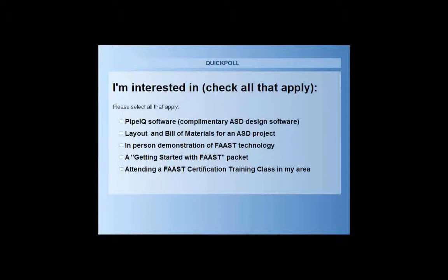However, the FAAST unit can accommodate other material. It could be PVC, copper, steel, ABS, PE, the flex black tube or the solid black. That's all dependent. The crucial element when you're designing a system is the inner diameter. Even if it's a retrofit application, the crucial element, if you want to use the existing pipe network, is the inner diameter, and we're listed within 1/2 inch to 3/4 inch inner diameter. So we can accommodate other materials, but as far as listed, it's the CPVC piping material.